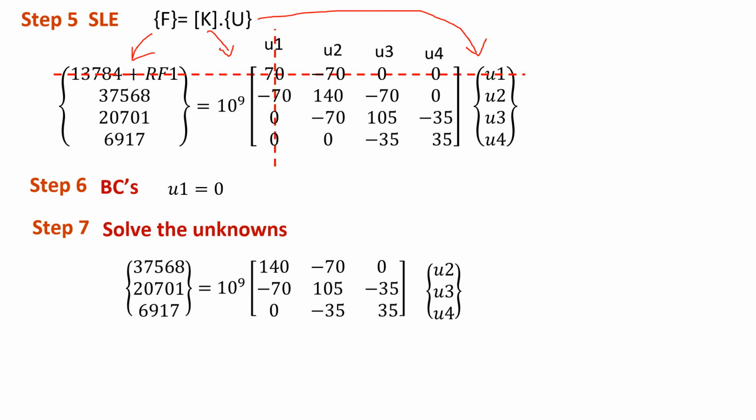So you have a 3 by 3 system. By using the calculator's equation-solving mode with 3 unknowns, you can solve for the displacement. We obtain all positive values because we only have one direction of load, which is going downward, and we assume the x direction is moving downward.